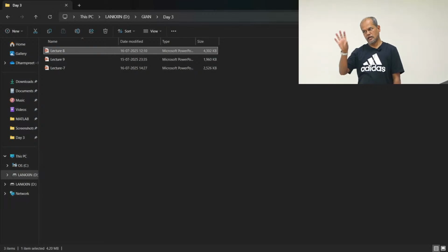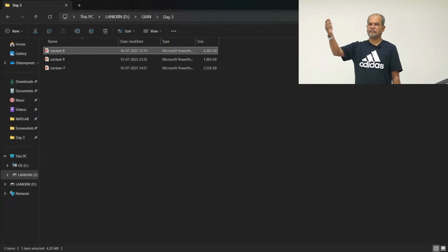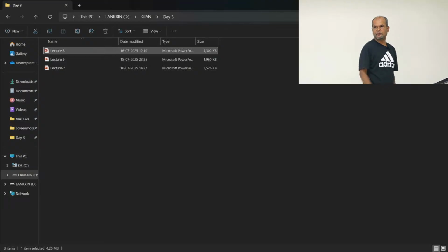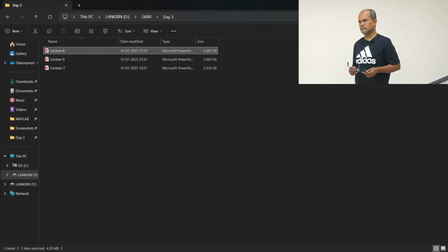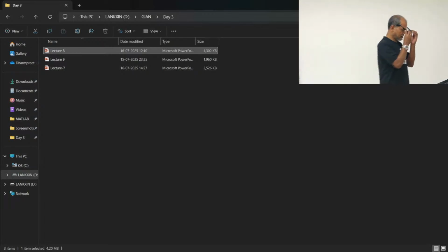And for frequency, in some countries it is plus minus 0.25, some plus minus 0.5, like 50.5 and lower 49.5. But in some cases, 49.75 and 50.25 is the limit. So, for low voltage it is 5%, and for high voltage it is 10%, plus or minus. Thank you, sir.